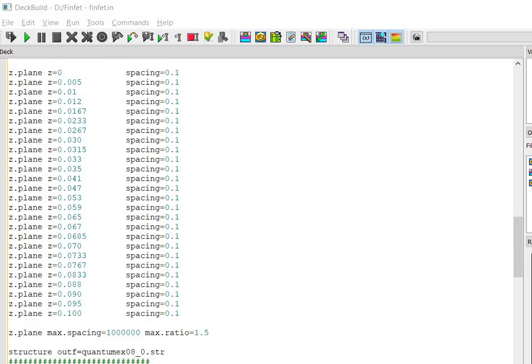Next is the Z plane. Define the Z plane for 3D mode only. Z planes are created at the front and the back of all regions and at the specified Z location. You can save the file in two formats, structure file and command file. The structure file is a format used by the Silvaco programs including Tonyplot and Atlas. Silvaco structure file has the extension .str. Choose any name and use the extension .str.